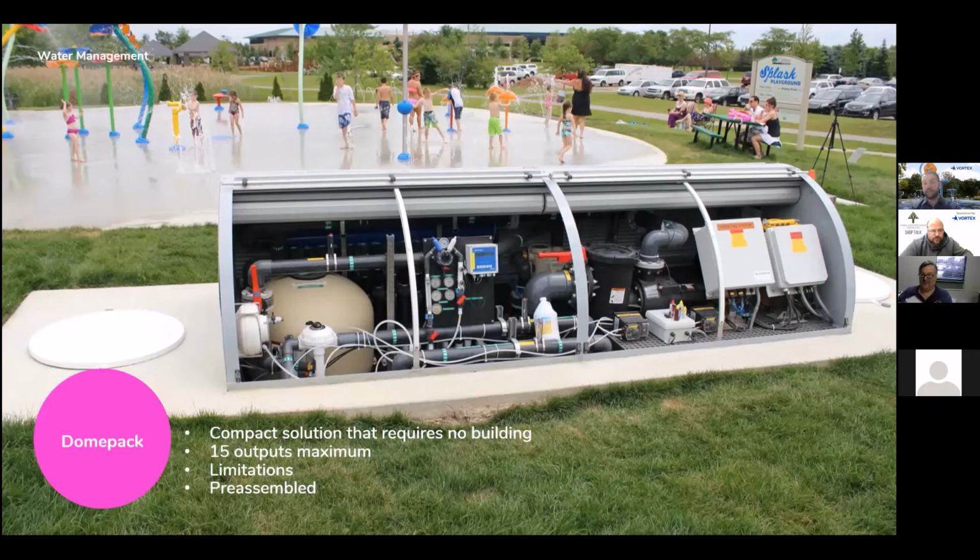Now, there are some limitations when it comes to GPM and maximum outputs or maximum valves. We have a 15 valve limit. So if we have 40, 50 features on a splash pad, which I've seen before, a dome pack isn't going to work. But again, it is very advantageous for situations where a site does not have an existing building already, and we don't want to go through the trouble of bidding out the construction and supply of a building,